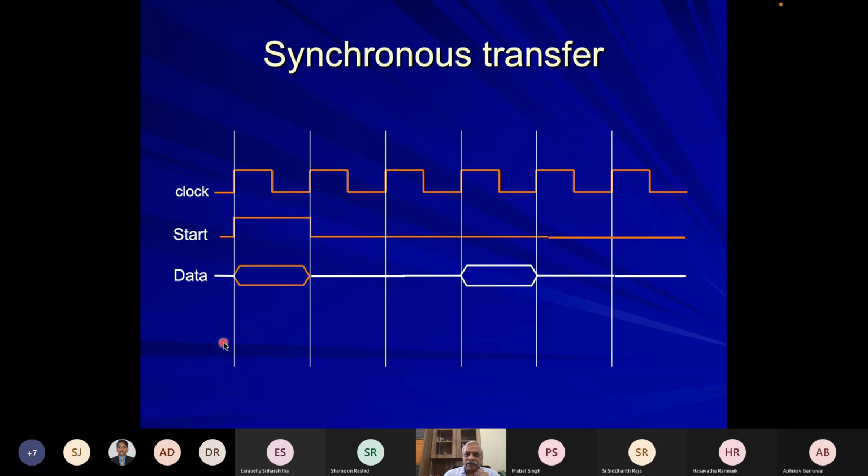The way synchronous and asynchronous buses differ is that in synchronous bus, all transitions happen at certain clock edge. Okay, so here we are showing that the initiator would send a start pulse. It's one example only. All synchronous buses may not exactly do it this way. So this cycle is being used to send address, and this control signal start indicates that this is the starting of the transaction.